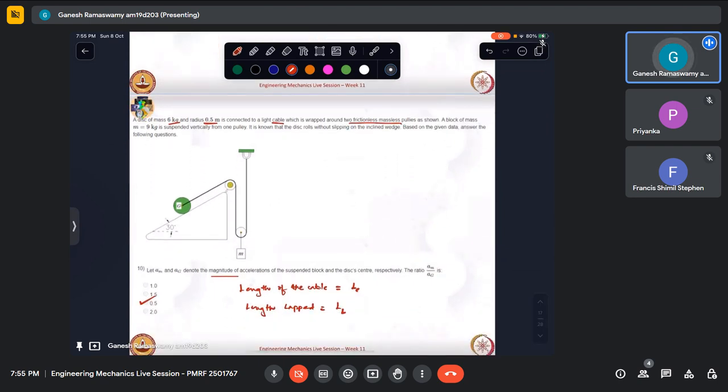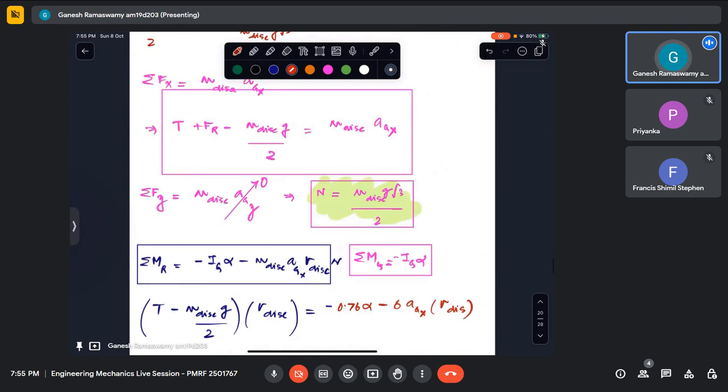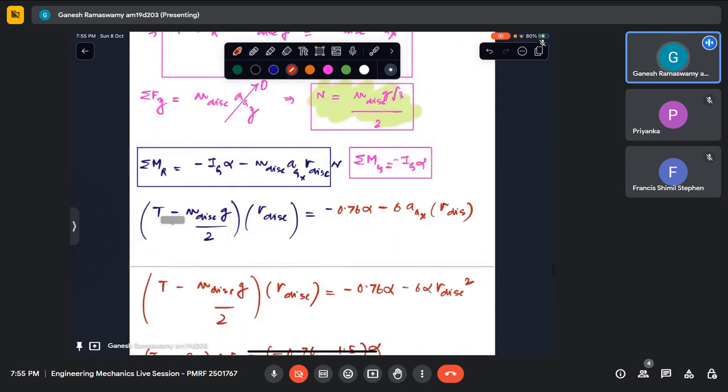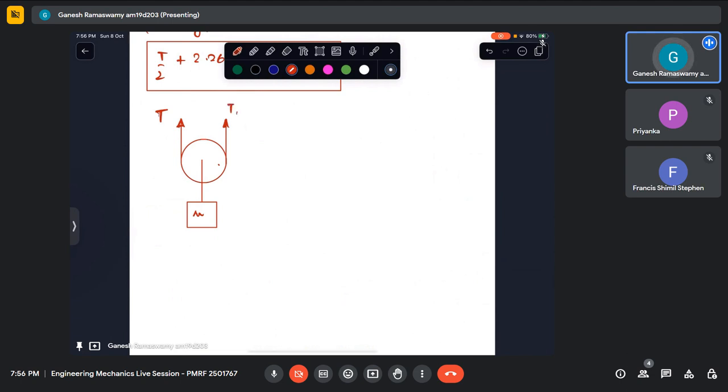Otherwise, if we need to add friction also, then we will have to account for friction, how we studied. So the idea is not to involve all the complexities into this question. It is just to emphasize what the main idea towards understanding this is. Even if there were friction, then if this was T2, this is T1, by knowing the friction coefficient, we can relate these two. So that won't be an additional unknown. Once you know one tension, you can easily calculate the other given the friction coefficient.